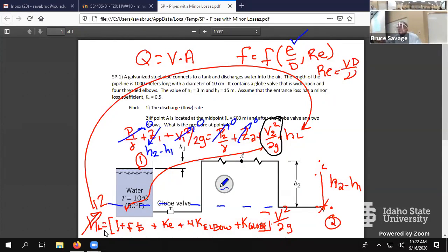That's where I messed up, for some reason I thought the friction factor was just epsilon over D, not a function. So we have to use the Moody diagram or one of the equations to find the friction factor, and that includes the Reynolds number. Unless you're a really good guesser, you're not going to get the correct friction factor the first time, so you'll probably have to iterate.